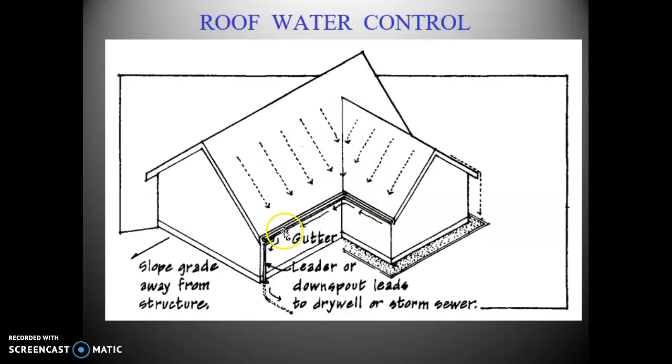The whole idea behind a gutter is you get the water away from your foundation system. This is your grade, your slope of your land. You guys now know that foundations are always going to be above the ground by 6 inches minimally by code. Therefore, what you do is you grade, or create a contour of the land, such that it moves the water away from your house. So catch all the water on your roof, direct it to a specific area, and get it away from your foundation. That is the key thing.